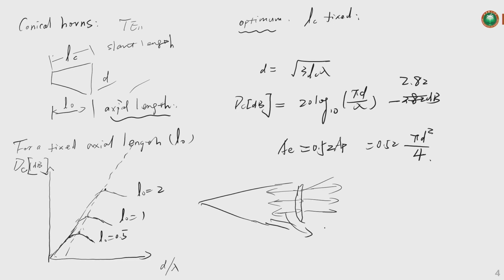This is going to lead to variations of amplitude and phase across that one. And then the wave impedance of the lens should be designed to keep the impedance matching between the air and the material.